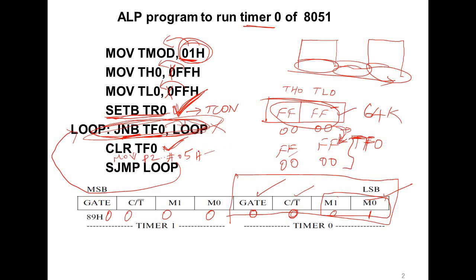Here you can produce output, and again make another loop. In the other portion, just reduce the count, changing the x-axis counts. Just have 3 or 4 sets of counts to give a shape to your waveform, and produce your output to a particular port through the DAC. This is how we design.